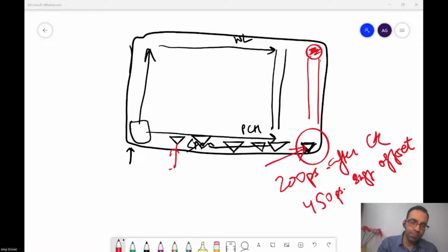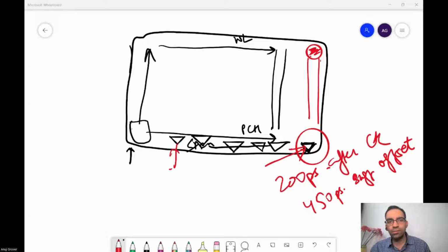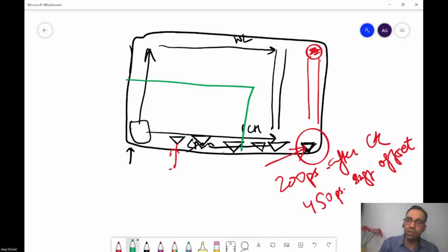Are you with me? Yes, sir. So to be able to do this right, we say that we will track the word line. Again, in a smaller instance, I wanted the sense amplifier enable to come at, let us say, 350 picoseconds.